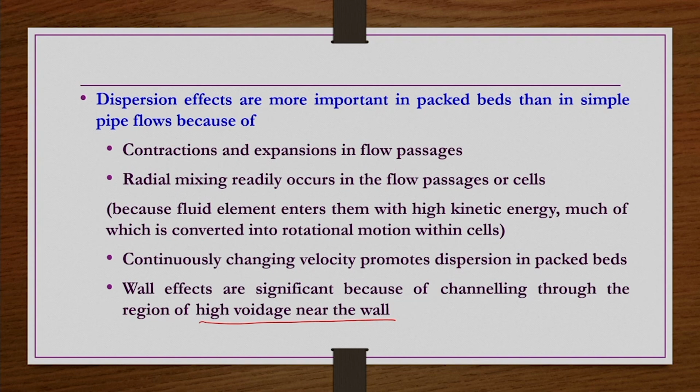That voidage is in general very high near the walls compared to the voidage at the center of the bed. Because of that also, wall effects near the wall induce dispersion in packed beds.